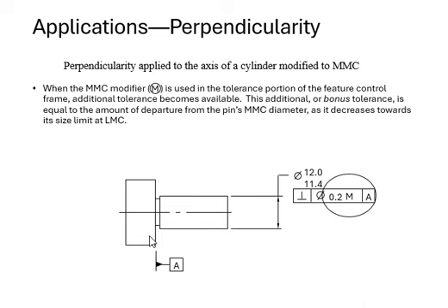You will study the flow chart, yeah, two different ways going where we make the decision yes or no by looking at this perpendicularity: are we going to apply that to a feature of size or not? And then you decide for the tolerance, you decide for the maximum material condition or least material condition, one of them, and then your tolerance, and then your datum one by one. You have to have these things in order for us to control the perpendicularity.